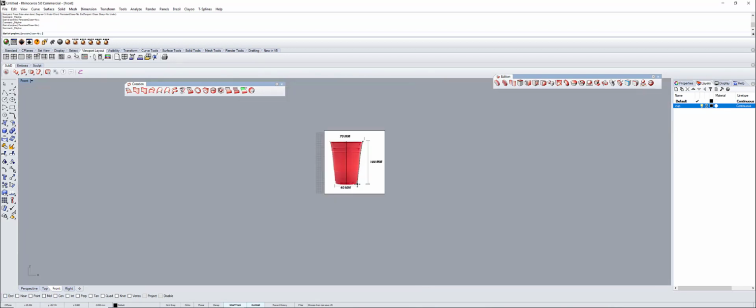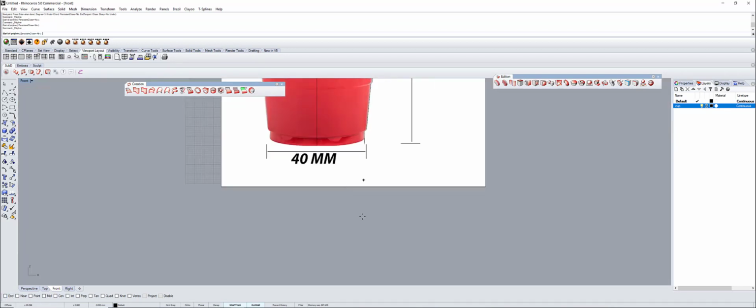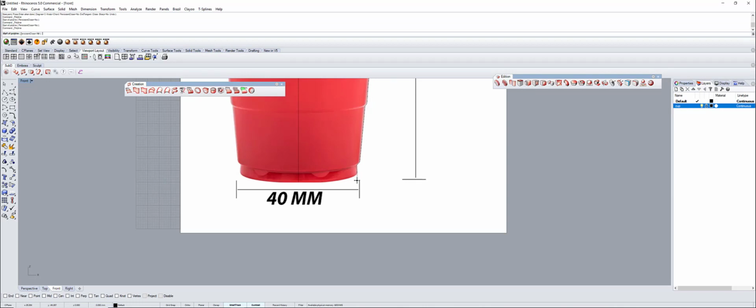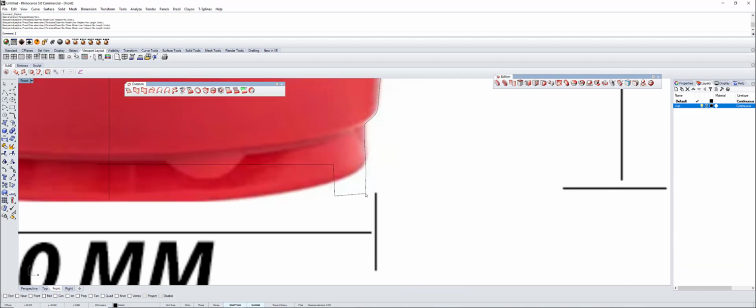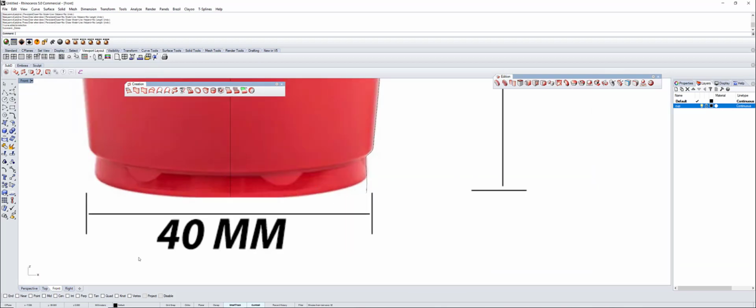So for example, I have this picture like this, and I think, oh yeah, the end is here. So I put it over there and I start doing the draw. At the end, I have to close this curve over here to make it only one. So when I'm going to go over here, oh no, it's not closed. So it's going to be an error over here when creating the surface. So this is why you need to use this. This helps.